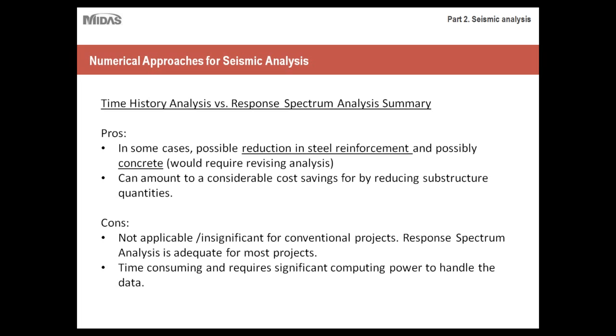If you don't have a numerical modeling program, it's really not realistic to do the time history analysis because all engineers, especially out on the West Coast, have numerical modeling programs that are very specific to seismic analysis to help them save on the time that they invest in it, because time history analysis is just so prevalent there. So those are the two things to keep in mind. One, make sure that you actually need it, and two, make sure that you're equipped to handle it if you do.